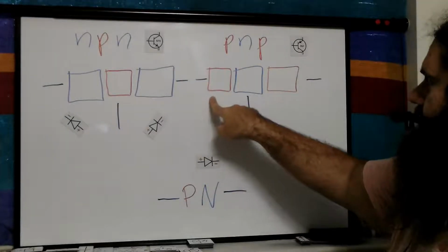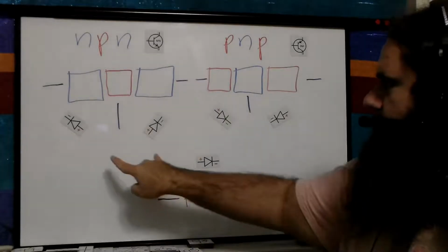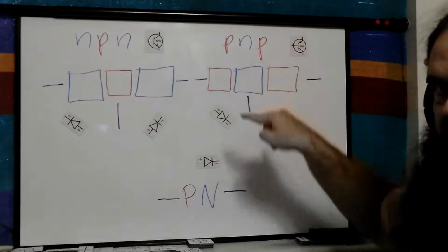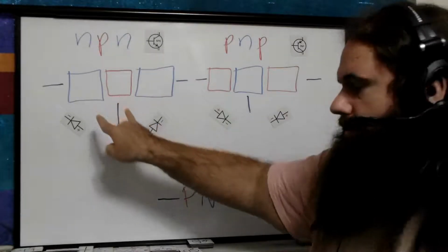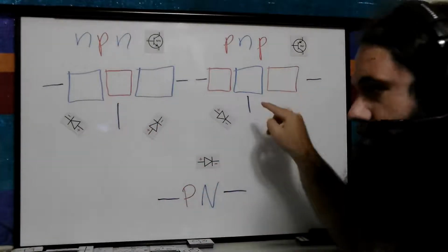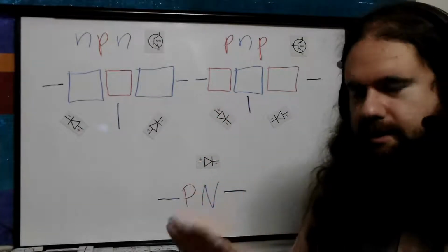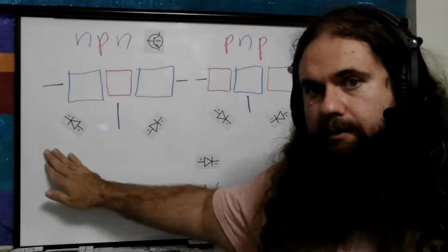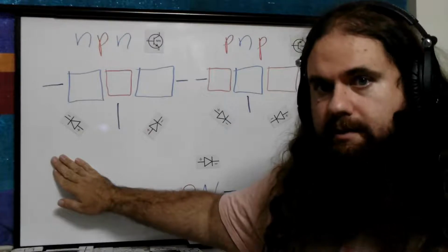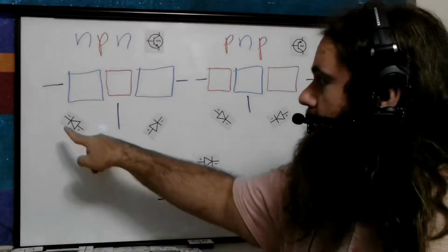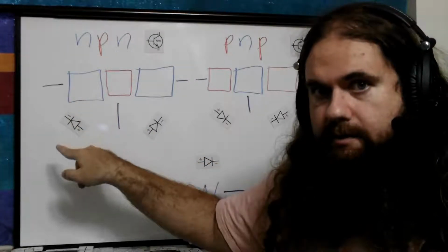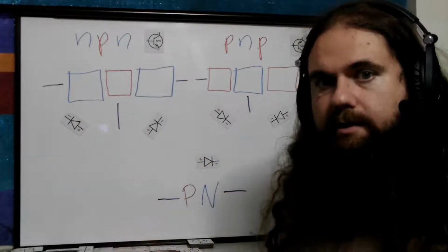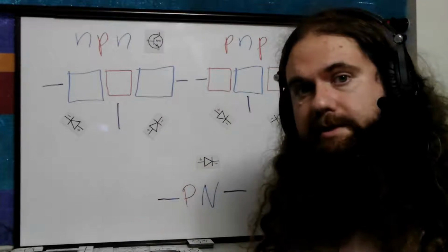These two pins, P-N, N-P. So this one you've got diodes facing this way, this one you've got diodes facing this way. It's not diodes, it's junctions. This junction is like this junction. This junction is like this junction. Think about junctions, not diodes, junctions. Remember how we can forward bias diodes? Well, that's what we do with transistors. These junctions, we will forward bias the junctions as if they were diodes, and whether we're forward biasing or not forward biasing makes the transistor behave differently.